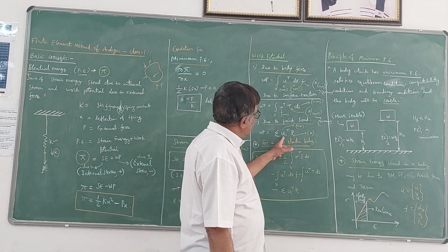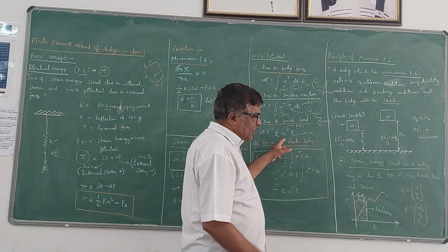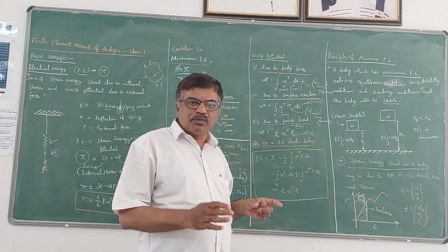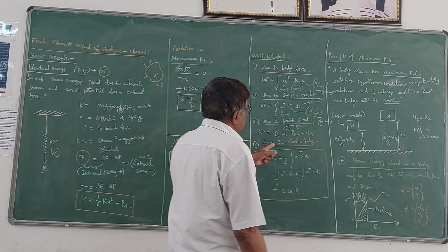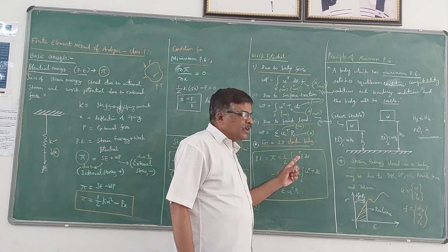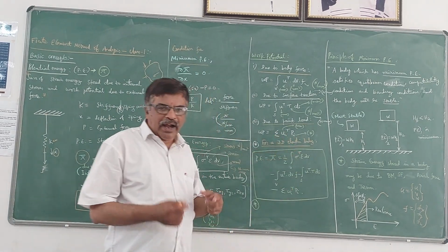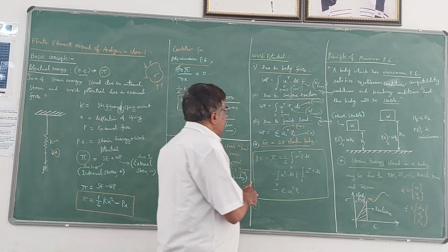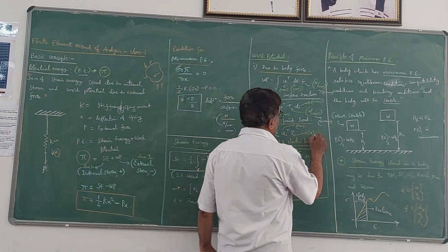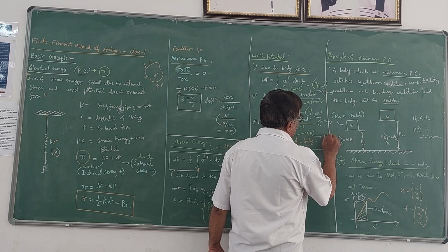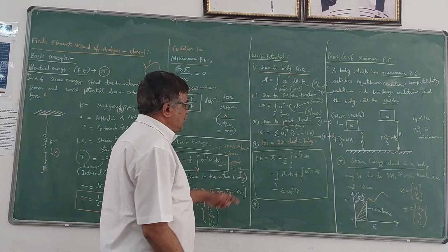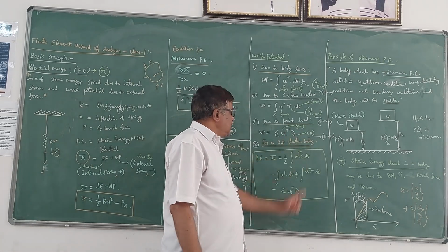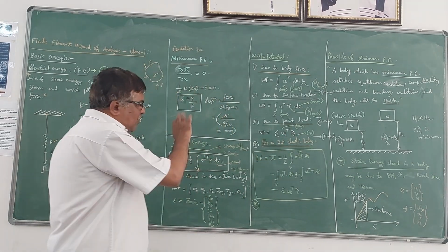Once again, at whatever point you take, at those points you should have the values of the displacement and the magnitude of those forces, given as PI. When you take the product and add, you get the value of work potential due to a point load, and when you multiply the units, you get Newton millimeter, because P will be in Newtons and UI will be in millimeters.